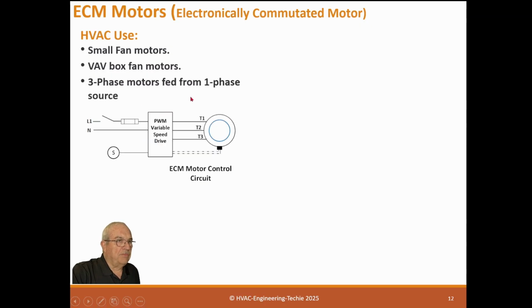A three-phase motor fed from one phase, typical. Have a single phase coming in. You have this pulse-width modulated drive, and the motor itself is three-phase, so it doesn't need a starting torque or anything like that. And it has a sensor that is actually feeding this pulse-width modulated drive of what to do.